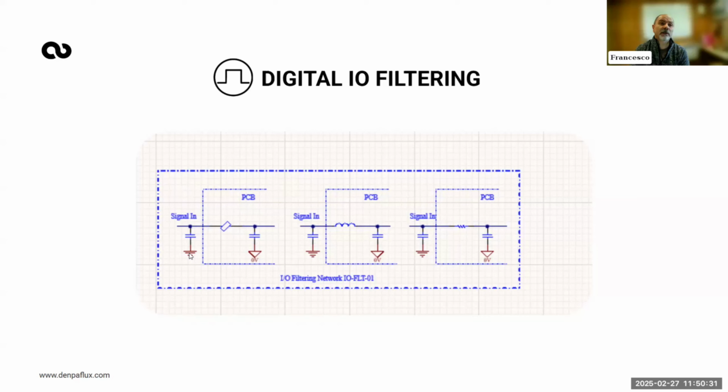You may notice that there are two different symbols here. One, you can see a kind of F symbol, another one 0 volt symbol. These two, let's call them 0 volt, they are connected together in one point. And I do this, I cannot show you the layout today, but I do this to improve ESD. In reality, if you create around the connector a kind of guard, you minimize the chance that when you have ESD, your voltage goes everywhere in your board in an uncontrolled way.